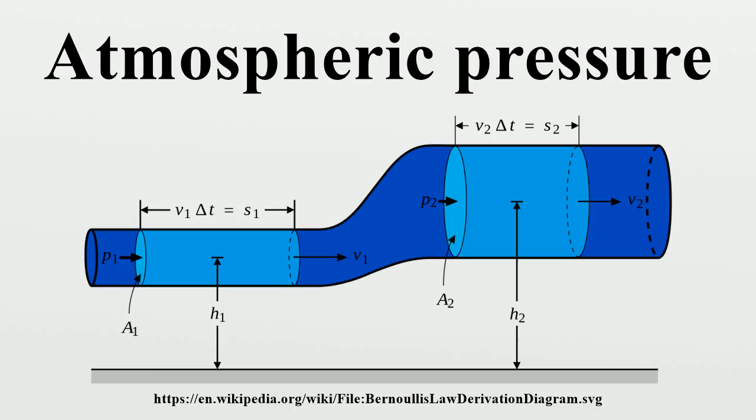Average sea level pressure is 101.325 kilopascals or 29.92 inches or 760 millimeters of mercury. In aviation weather reports, QNH is transmitted around the world in hectopascals or millibars, except in the United States, Canada, and Colombia, where it is reported in inches of mercury, with record highs close to 1085.0 millibars. The lowest measurable sea level pressure is found at the centers of tropical cyclones and tornadoes, with a record low of 870 millibars.